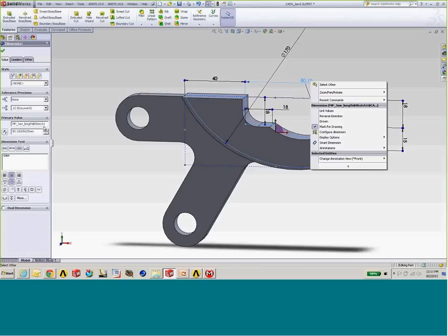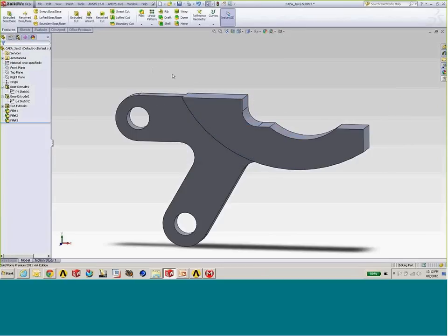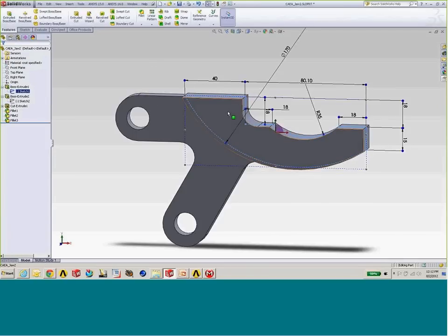So from a best practices standpoint, it's always a good idea to take a little time, go to your parameters, and give them realistic names, the names that I had shown on the previous page, so that when I'm doing an optimization or design of experiments on this, I know exactly what that parameter means. I don't have to do any kind of mental gymnastics to figure out what parameter zero affects in terms of that geometry. We go through our particular sketches and our operations.